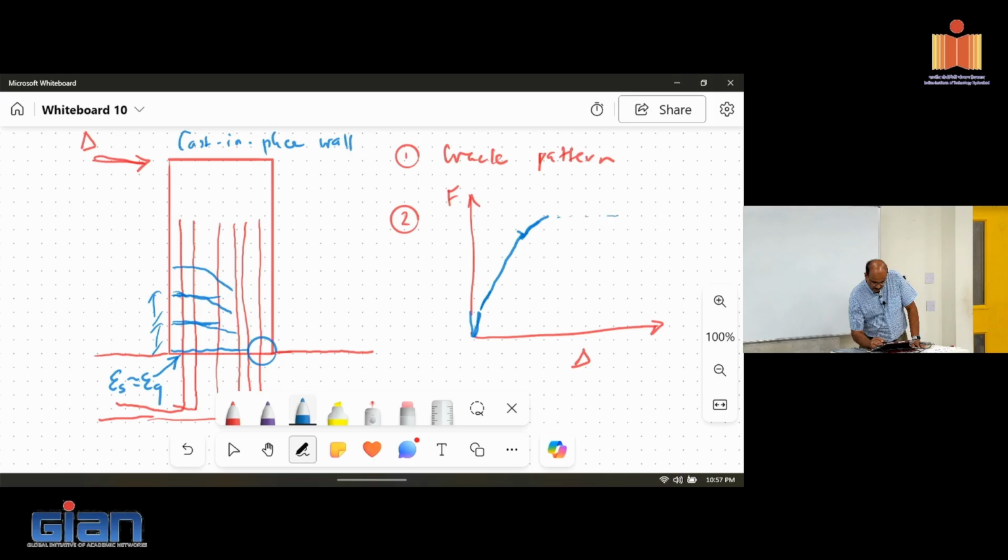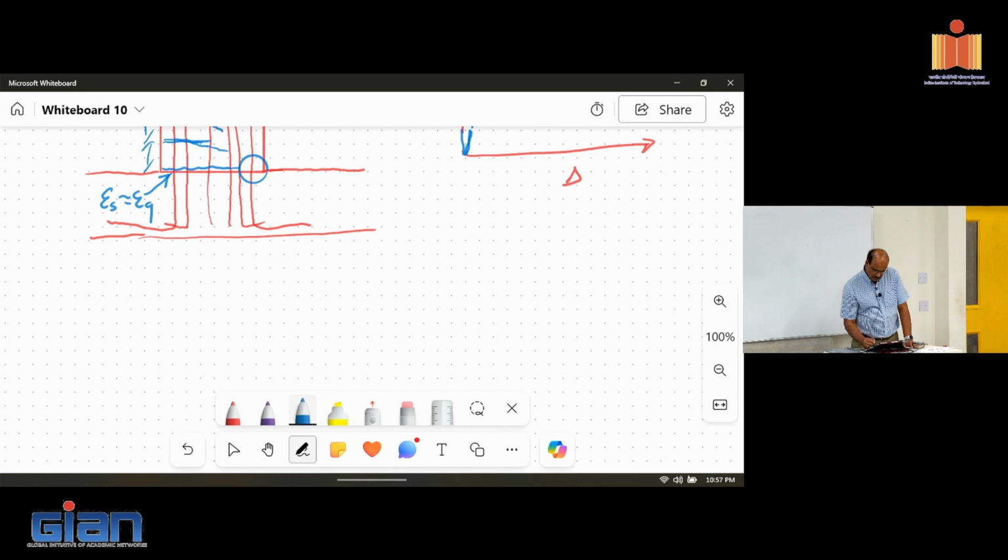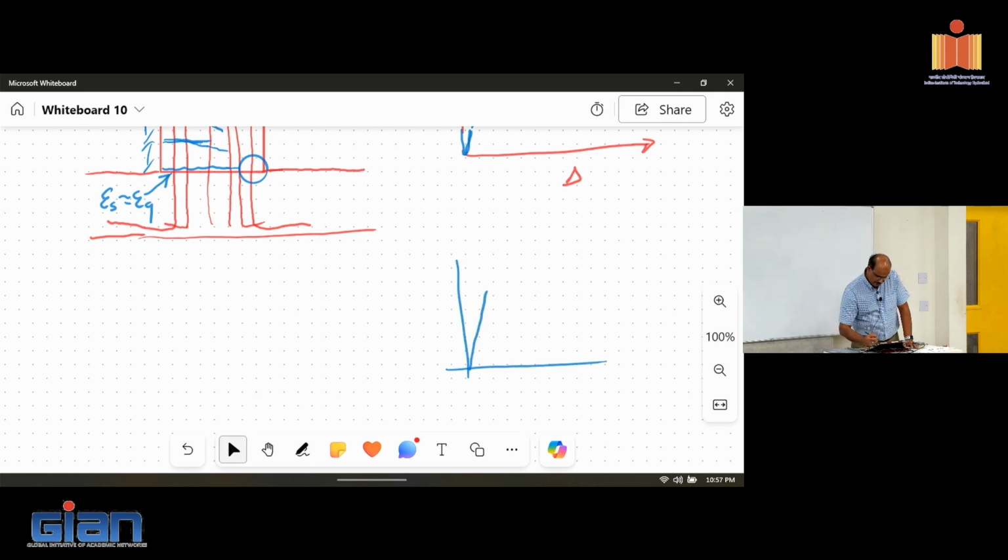I've noticed that some of you drew the line horizontally, and some of you think it's going to go further up here. Which one is correct? Strain hardening. Yeah, rebars typically have strain hardening. You know what strain hardening is, right? If I look at the rebar behavior, it's elastic, then you have a yield plateau, and then you go through this path.